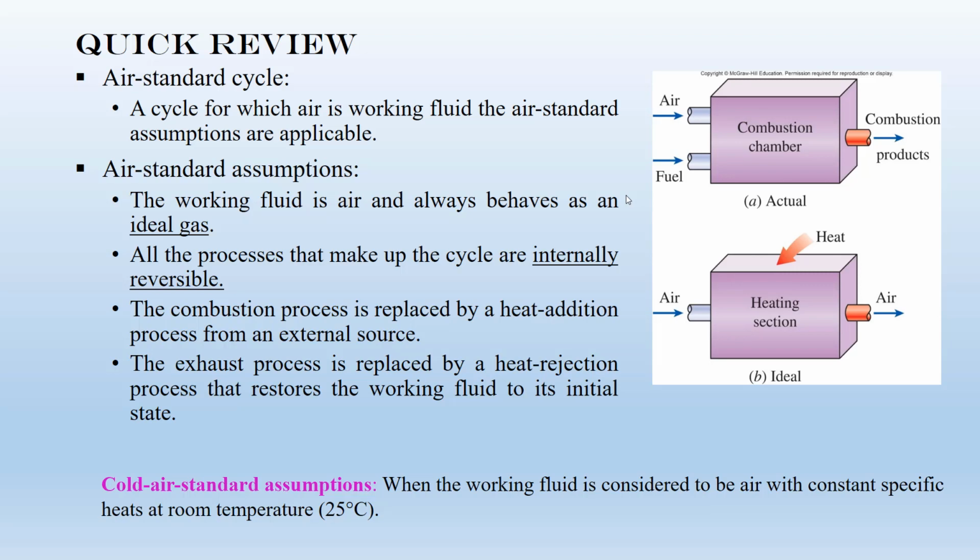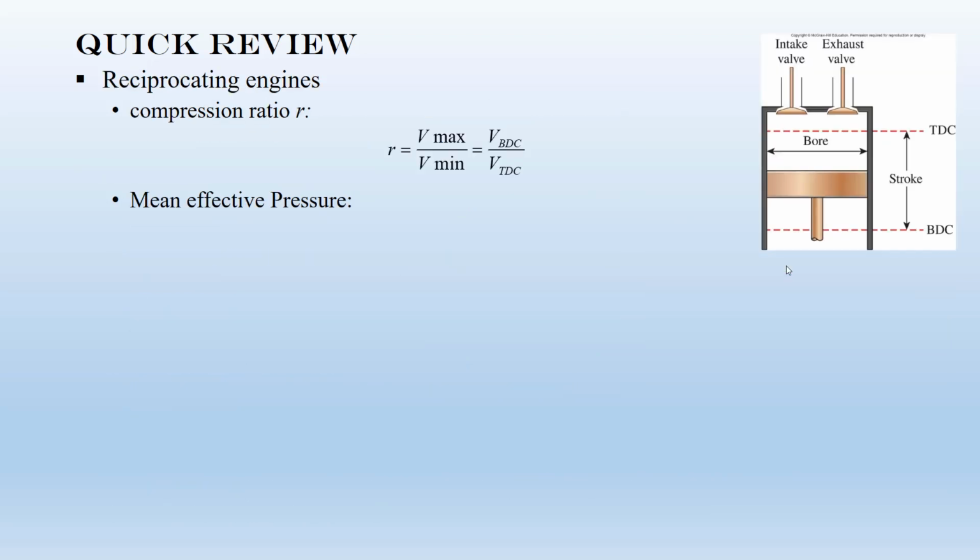Based on the air standard assumption, air is an ideal gas. You can use the ideal gas equation of state for the air, and we assume that all processes are internally reversible, and then we just cancel the fuel. We assume that air is the only fluid in the process, and heat is added from an external resource. Then we discussed the cold air standard assumption. So if you are asked to solve a problem with the cold air standard assumption, you can use the specific heats of air at room temperature, or 25 degrees centigrade.